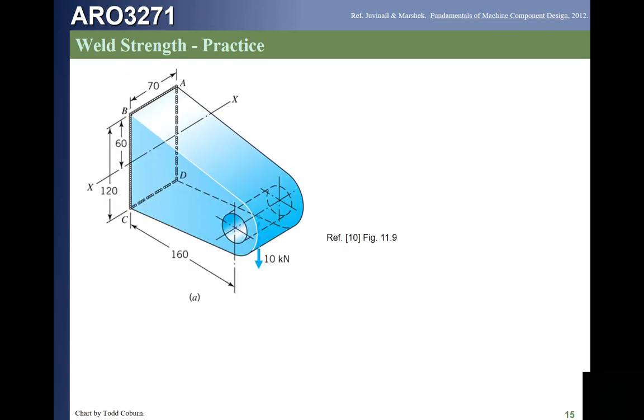Okay, here's another one. This one, if we look at this, we can use the approach from last time to solve, or we can also use our simplified box weld approach. We saw that while the force is in plane, it causes a moment that's in plane, which means it gives out of plane components. So this uses the out of plane approach. We're going to calculate the I of the weld and solve it that way. And these are the component reactions, and we saw these last time.